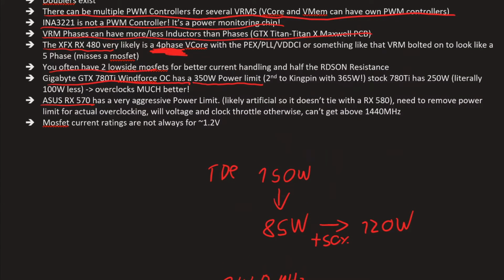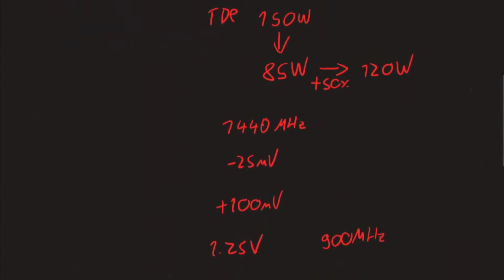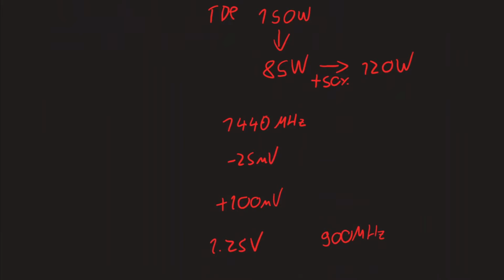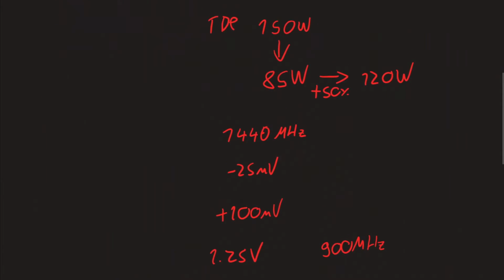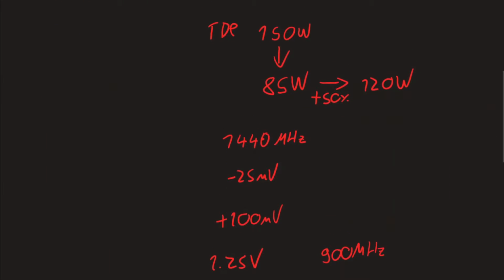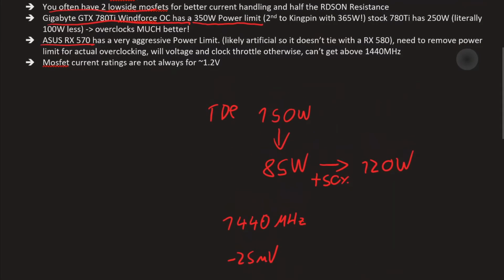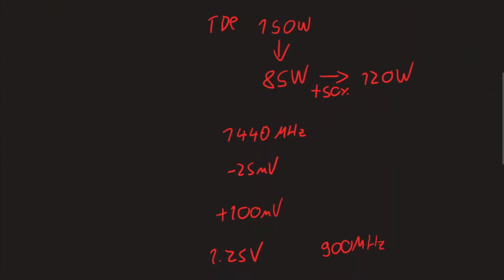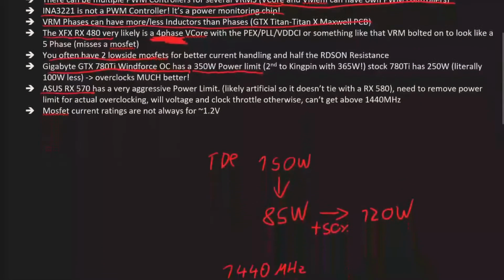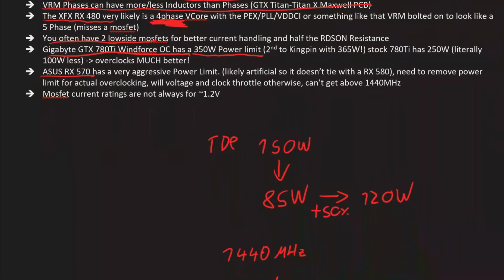And yeah, that's not great. And as of today, like 2 days ago, I tried flashing my card. I tried to flash a custom BIOS on it that gives it a power limit of 200 watts, because I didn't want to overload the VRAM just yet. I would probably end up giving it 300 watts or something. And yeah, sadly, custom BIOSes don't work anymore on AMD cards, because AMD locked down the drivers. The drivers won't run with a non-signed custom BIOS.